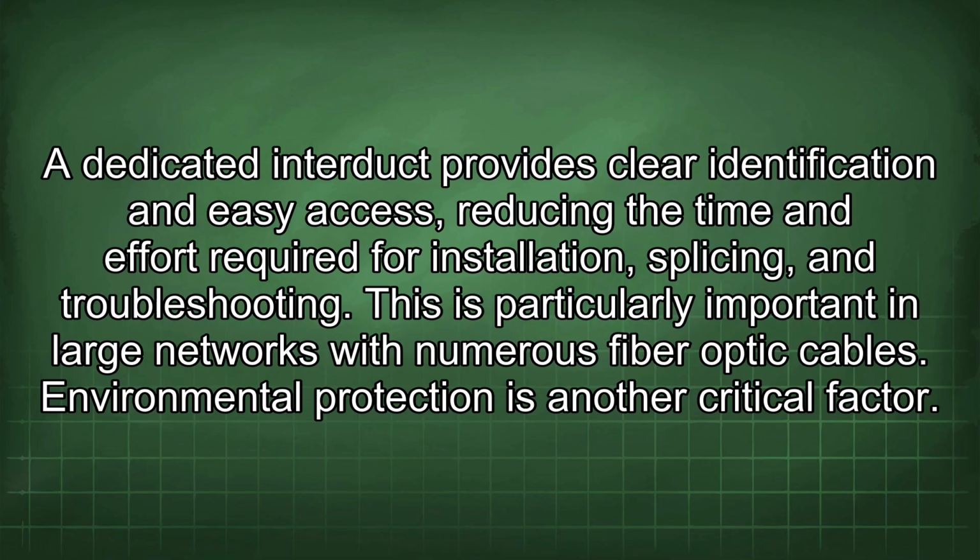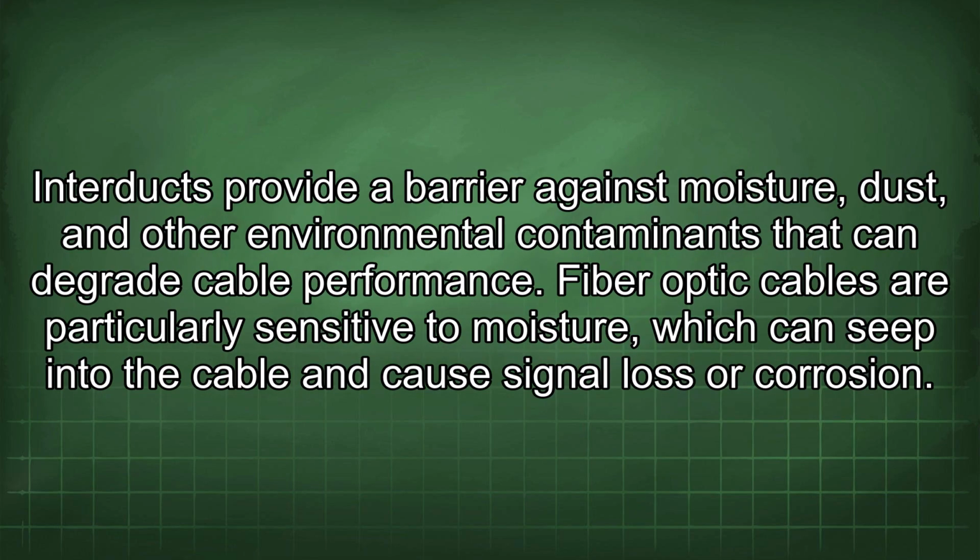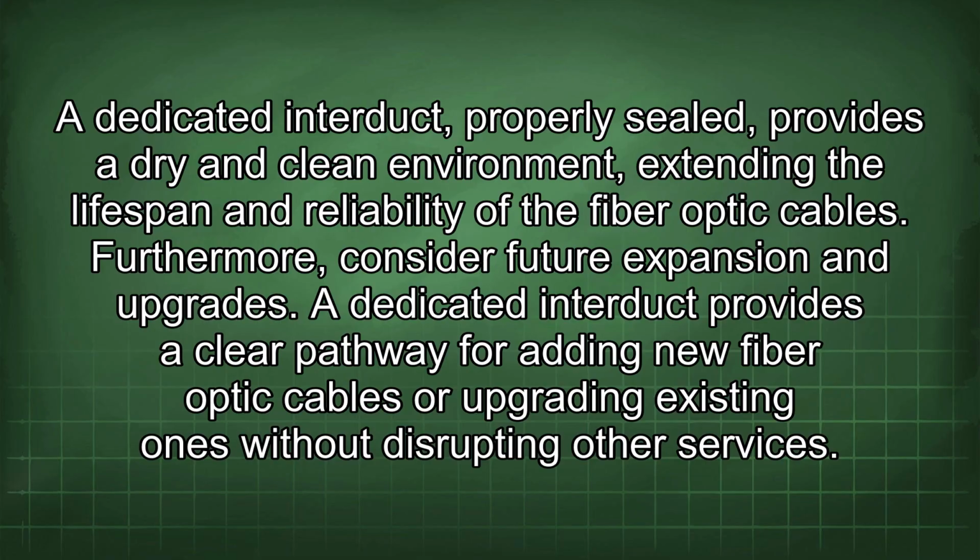Environmental protection is another critical factor. Interducts provide a barrier against moisture, dust, and other environmental contaminants that can degrade cable performance. Fiber optic cables are particularly sensitive to moisture, which can seep into the cable and cause signal loss or corrosion. A dedicated interduct, properly sealed, provides a dry and clean environment, extending the lifespan and reliability of the fiber optic cables.